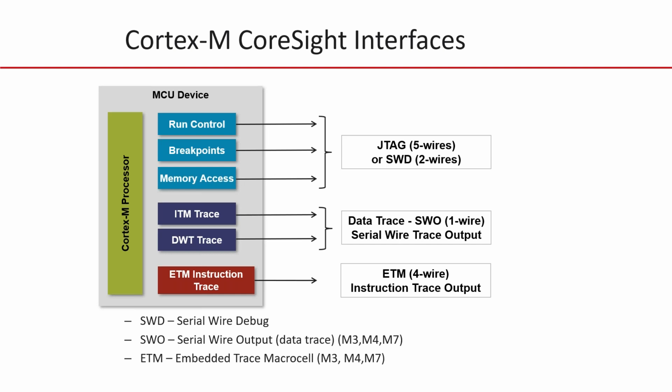We have a similar situation where we have the embedded trace macrocell. This takes an additional 4 pins, but these will almost certainly be multiplexed with GPIO. So we need an additional script file to convert these from GPIO to be the trace pipe.